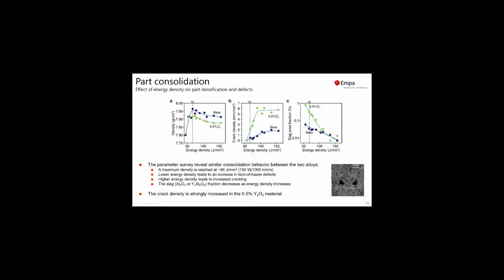If we go for lower energy densities, then we saw lack of fusion defects, which is not surprising. If we go for higher energy densities, then we see for both alloys increased crack densities, but this effect was much more pronounced for our ODS alloy.